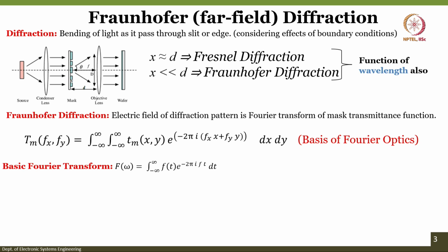Simply, if you consider one sine wave of one frequency only, it has only one component in the frequency domain, but when you plot it in the time domain, it extends towards both sides to infinity. On the other hand, if you take a small square wave, when you draw its frequency response, you will get a sinc function. The sinc function is again, as I mentioned, extended on both sides in the frequency domain. Okay. So, these are basic fundamentals of the Fourier transform which you should know.